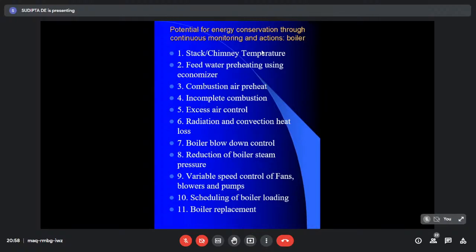But the incomplete combustion possibility is there in the carbon combustion process. If there is no combustion of that carbon content, it is identified in the ash sample. In any big boiler, be it a power plant boiler or a process boiler, sample collection of the ash is a standard protocol, and those samples are examined in the laboratory. If you find carbon particles in the ash, then you have to be very cautious, because some incomplete combustion has happened.